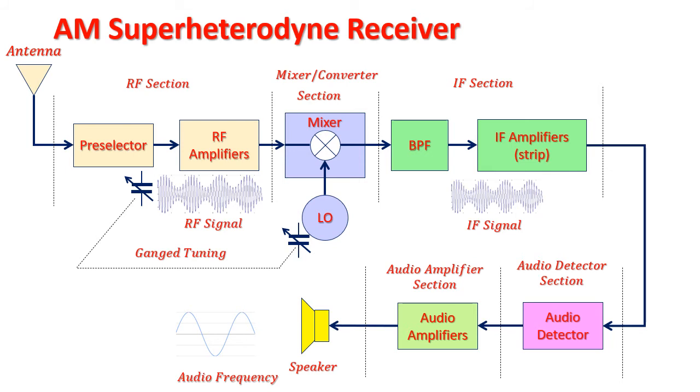The preselector also reduces the noise bandwidth of the receiver and provides the initial step towards reducing the overall receiver bandwidth to the minimum bandwidth required to pass the information signals. The RF amplifier determines the sensitivity of the receiver. It is also the primary contributor of noise and predominant factor in determining the noise figure for the receiver.